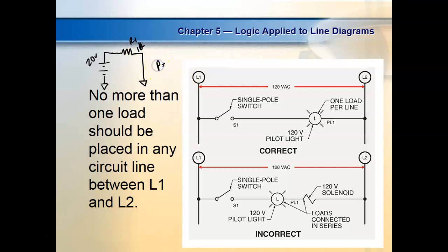So one of our power formulas is V squared over R. So I'd say power would be equal to 20 squared over 1K. And what would my power be? No, it's going to be watts. Power's in watts, right? Milliwatts. Okay, so let's raise this up to 40 volts. So I double the voltage. So I come over here, this is going to be 40 squared over 1K.